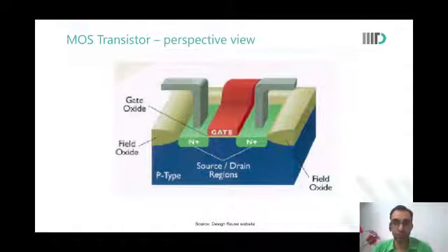Charge flows. I have seen it in a diagram. So don't get confused. If the inversion layer is not there, then we say that from gate to silicon surface and silicon surface to the edge of depletion, there are two capacitances in series. But at that point, there is no inversion layer. There cannot be a capacitance between the inversion layer and the edge of the depletion region, because they are electrically connected.